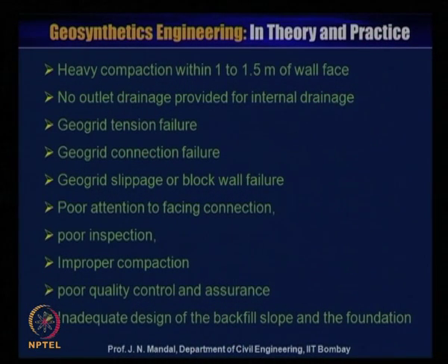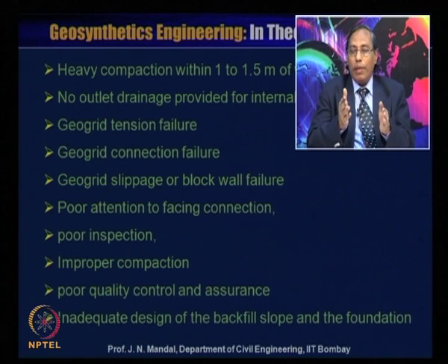And the reinforced soil structure can fail due to tension failure. Then the geogrid may have a connection failure. There is geogrid slippage or block wall failure. The block wall itself will fail. And sometimes also the placement of the block is not proper. Sometimes the block has been placed upside down, and the structure collapsed. When you look closer to the wall, you find the block has been placed upside down. So that was the reason for the failure.